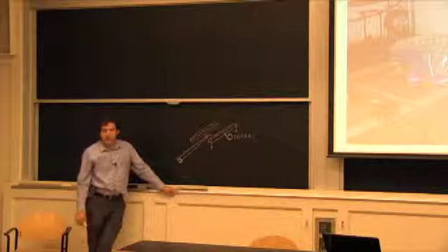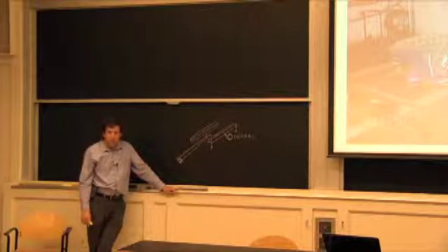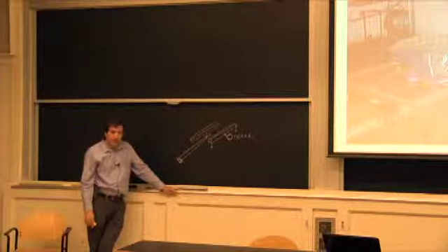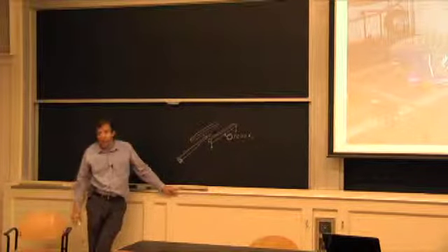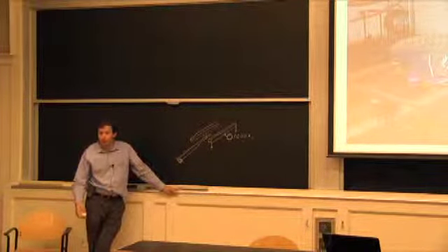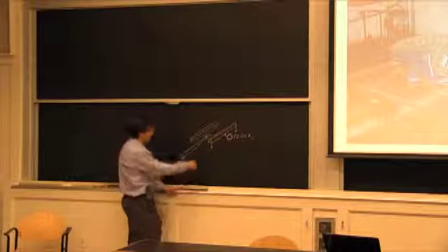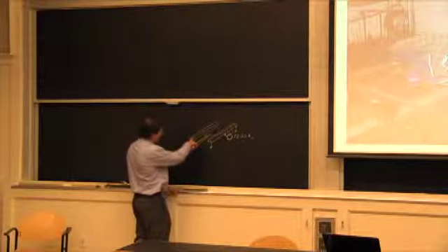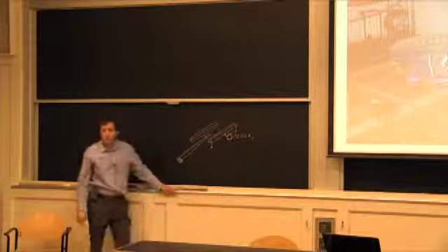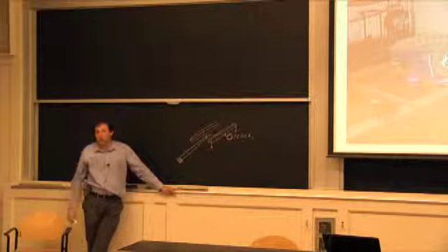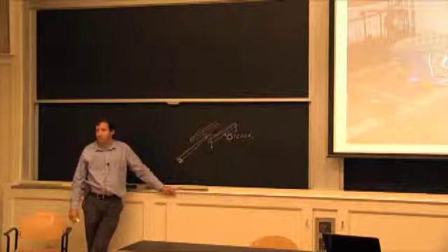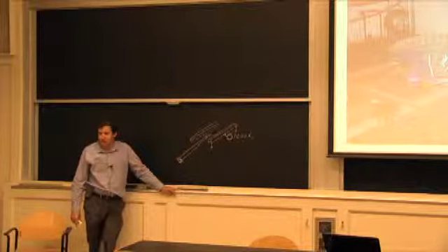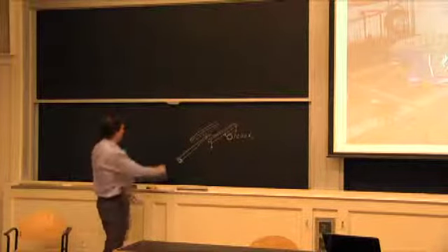And that's something that becomes a little more complicated to evaluate, but talking to people that have been building trailers for a long time, they told me as long as I make my welded connections at the corner, that'd be more than sufficiently strong to resist the torsion. Yes? They may not have known the term racking. Yeah. For a structure like this.